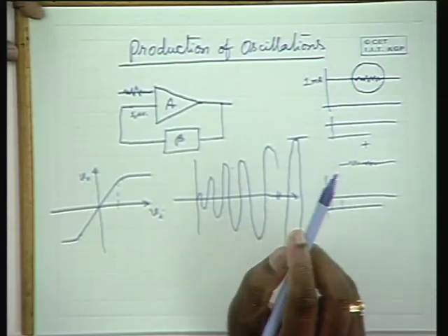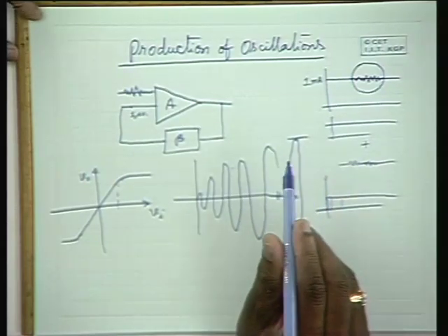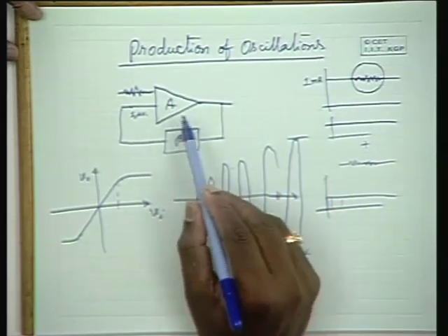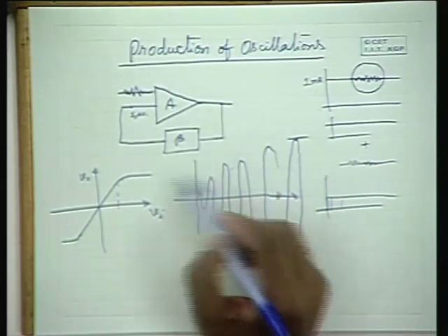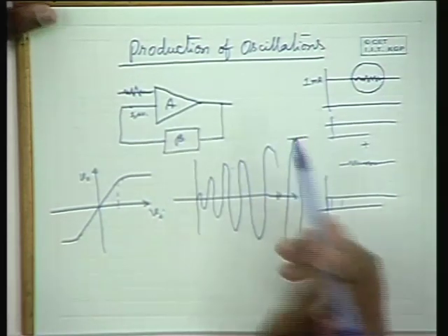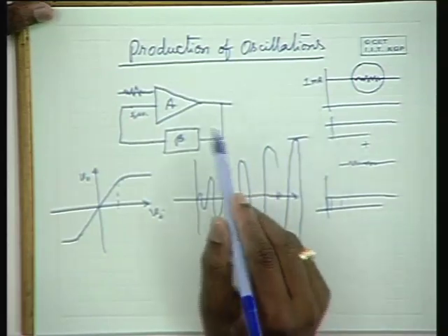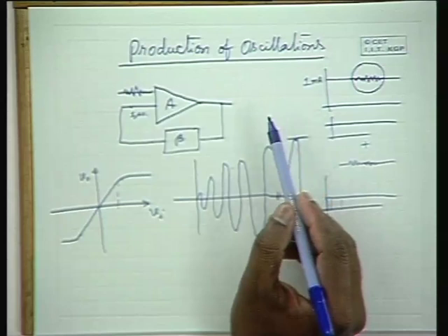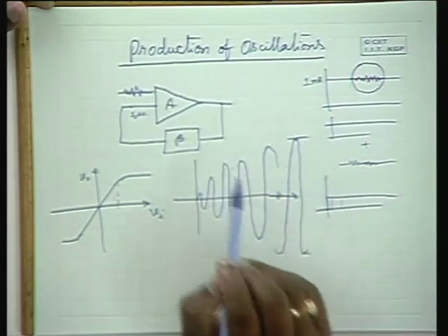So what difference there exists when A beta is -1? If A beta is equal to -1, naturally the oscillations do not get added in phase at the input, and you won't get oscillations at the output. You will only find some small amount of noise which is microscopically visible, so only that noise will be present at the output.